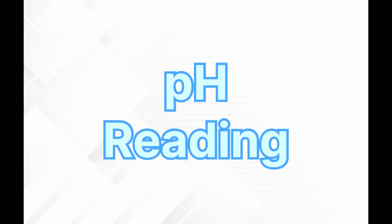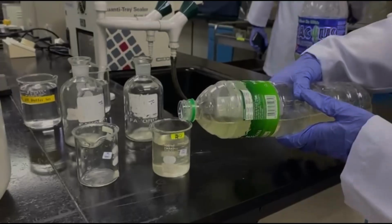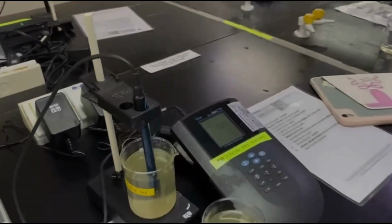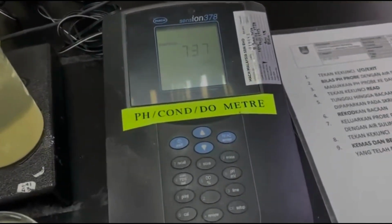The next experiment is the pH reading. The apparatus is a pH meter and beakers. First, we need 100 ml of each sample poured into the beakers, and start the pH meter. Then record the pH value once the reading has stabilized.